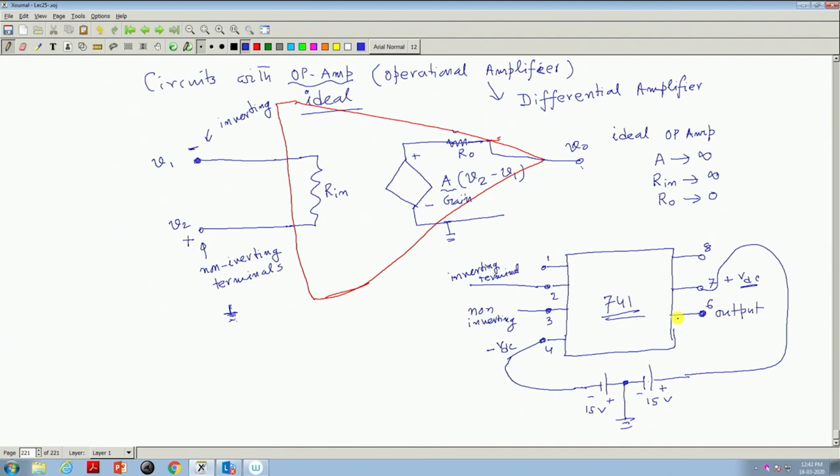This is how we identify these terminals. So, operational amplifier is nothing but a differential amplifier. It amplifies the difference of these two signals, that is V 2 minus V 1. V 2 you apply with respect to the ground. Where is that ground? No point in this chip. Ground is what you have created while giving supply to this op amp. We will not go deep into how it is realized with the help of transistors. This is outside the scope of this one.